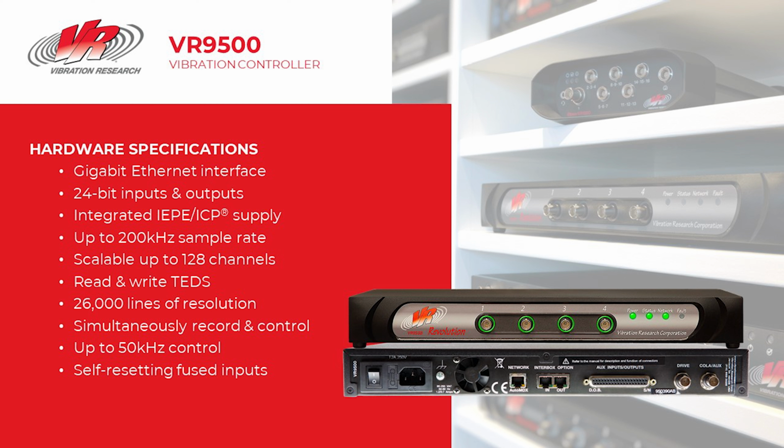One of those things would be using that to connect to a chamber so that you can run while the vibration test is running. If the chamber stops for some reason during a shake and bake test, you can stop the shaker so that the product does not have more hot-cold testing being done to it while the vibration test is stopped, and vice versa. So that communication can be key while you're running shake and bake testing, as it's called.